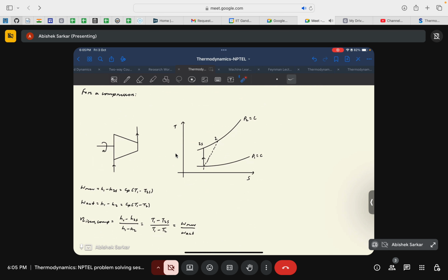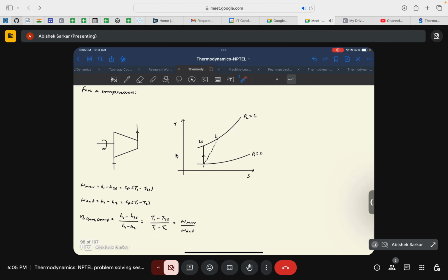If you recall, when we discussed the Rankine cycle, there was a component of the Rankine cycle, the pump, where the fluid was pumped to a boiler at a very high pressure. So it essentially increased the pressure, which resulted in a high boiling point of the working fluid, which gave us a higher range of temperature heat input, which increased the efficiency of the Rankine cycle.